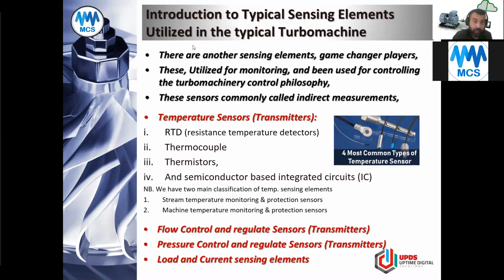Why am I wasting our time explaining these kinds of sensors? Because this is your open gate for Industry 4.0 or digitalization. The vibration sensor itself, as a standalone sensor, can't take the decision alone. Sometimes this decision comes at the last stage before the failure. But if you build some kind of algorithm to know what the temperature sensor is saying, what the flow sensor is saying, and what the pressure, load, and current sensors are saying, you can make some kind of logic.